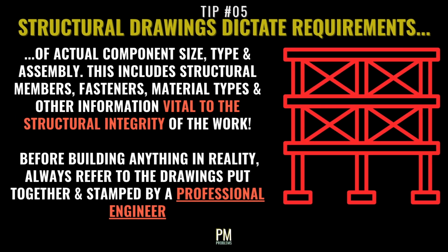And my last tip is certainly not the least, and in hindsight, I very well could have put it first. Refer only to structural drawings for actual component size, type, and assembly when it comes to doing any work whatsoever to the building's structure itself. Which is to say, any portions of the building or structure that are actually holding it up and keeping it stable, in comparison to details related to non-load-bearing portions of the work or finishes, etc.